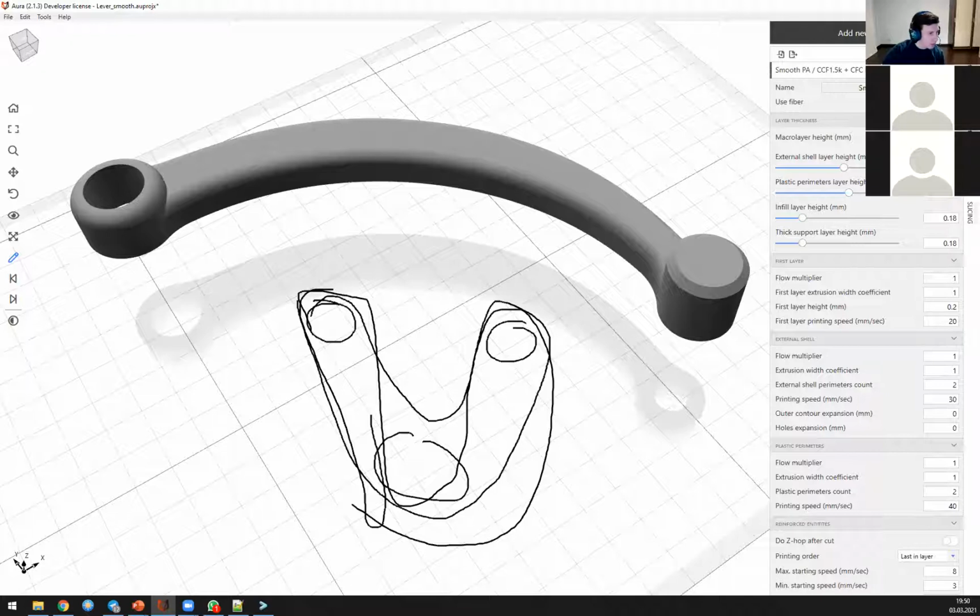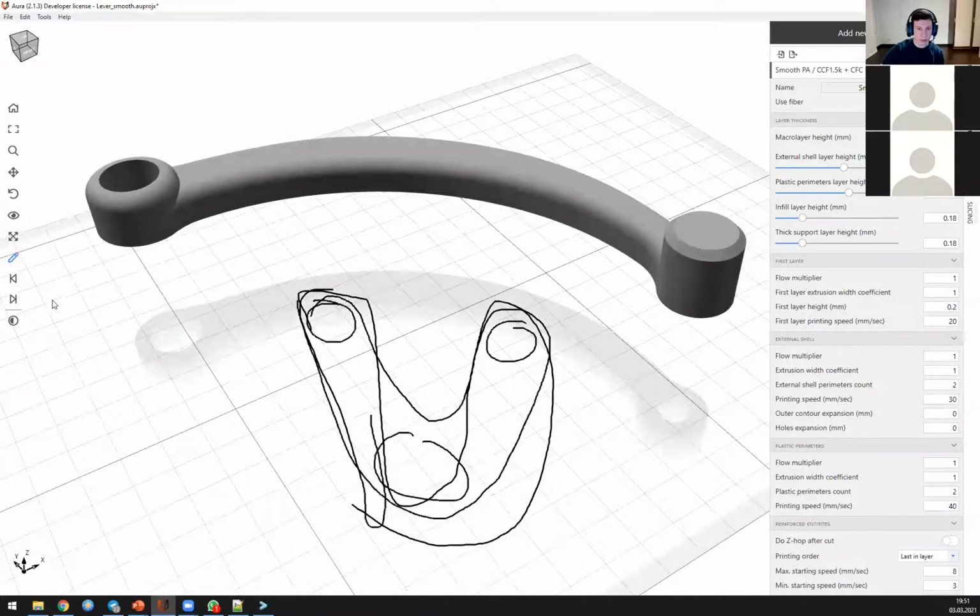Why shall it not be possible to construct the parts completely in the CAD? Well, that's what you usually do. You can construct the part completely in the CAD system. You can draw your masks in this CAD system as well, then save it as a single step file. And then you can open the step file and apply all the settings that you need to the mask models.